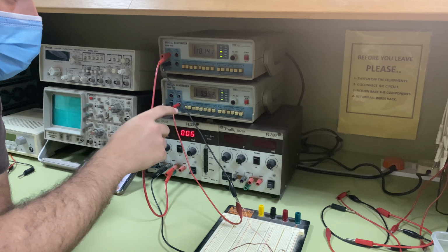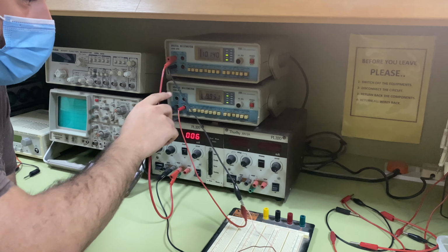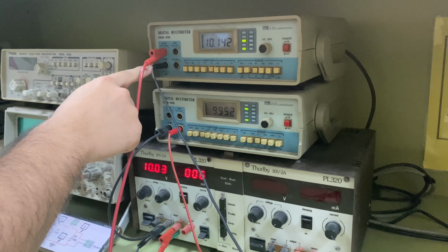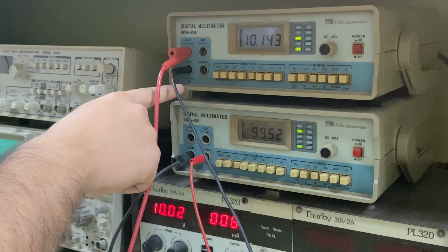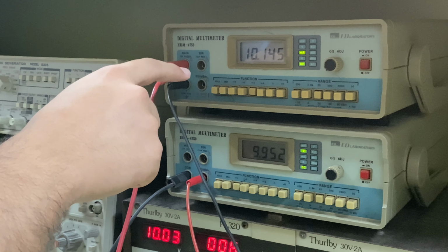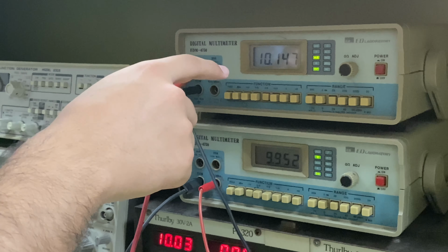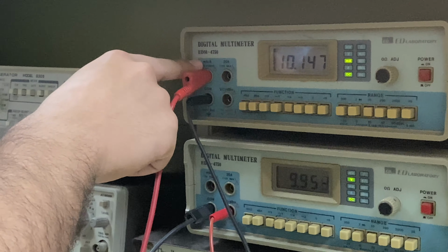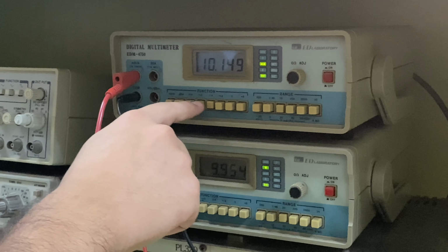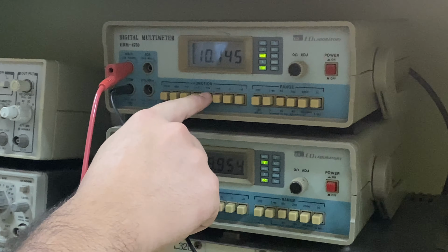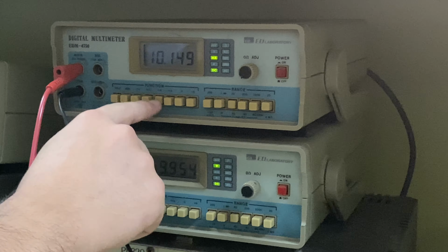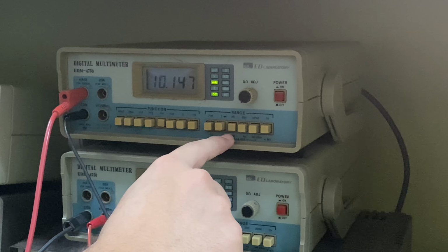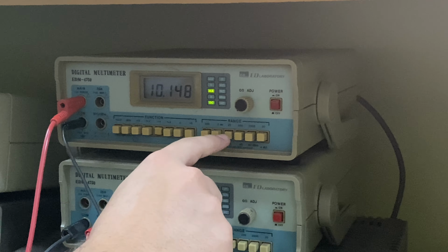For the first multimeter, we connected it as an ammeter. And as you see, we always connect the black wire to the common as ground. And as we want the multimeter to work as an ammeter, we connect the positive terminal in this plug. After that, we choose the DC ampere function to measure the ampere. And for the range, we try until we reach the proper range.